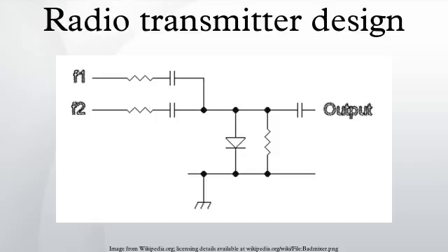Frequency multiplication. While modern frequency synthesizers can output a clean stable signal up through UHF, for many years, especially at higher frequencies, it was not practical to operate the oscillator at the final output frequency. For better frequency stability, it was common to multiply the frequency of the oscillator up to the final, required frequency.